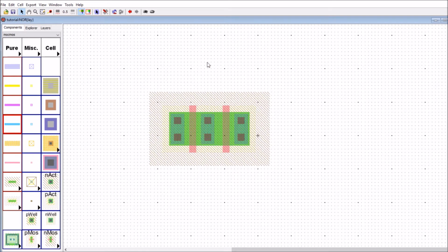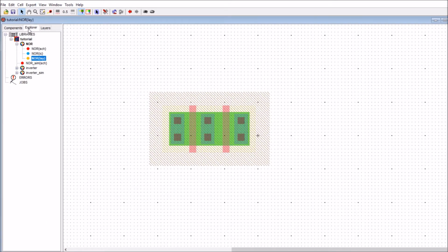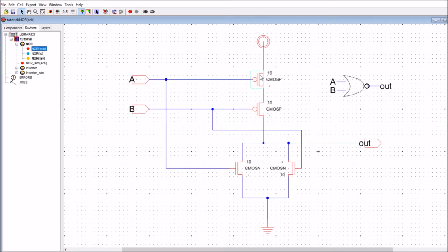So let's create the two PMOS devices in series. Again, let's have a look at the picture here from the schematic. From the schematic, we've got two PMOS devices which are in series. By in series, what we mean is this internal connection here is going to be joined together. So in effect, if this is a PMOS device, then it's going to be holes that are going to be the charge carriers. They're coming from this side to this side. So that'll be the source here, and that will be the drain.